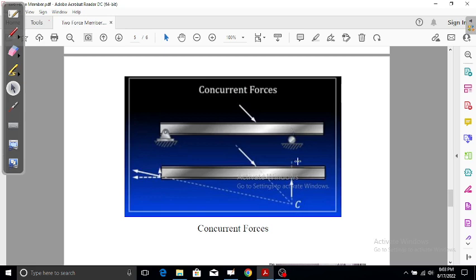It can go up. So if you look at it, this force can be projected downwards to point C of the roller, and the roller's point of action is already at C. This force is projected to point C, and this resultant, we can easily project backward along its line of action to point C. So again, see all these three forces: one external force and this resultant reaction of the pin and the roller, they could all be converged and concurrent at this point C. So whenever you look at a system like this, you will call it a concurrent force system, but this beam will be treated as a three-force member.